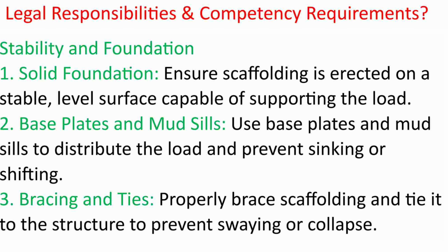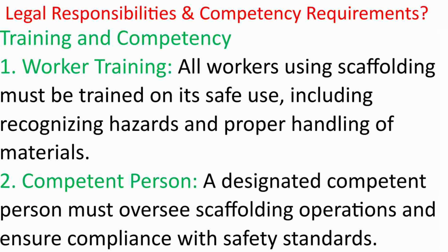Stability and foundation. 1. Solid foundation. Ensure scaffolding is erected on a stable, level surface capable of supporting the load. 2. Base plates and mud sills. Use base plates and mud sills to distribute the load and prevent sinking or shifting. 3. Bracing and ties. Properly brace scaffolding and tie it to the structure to prevent swaying or collapse.